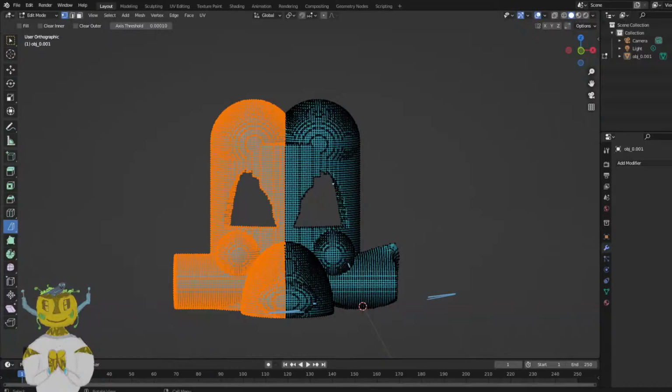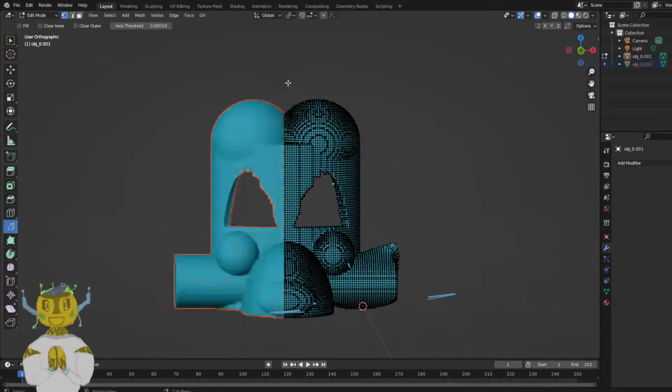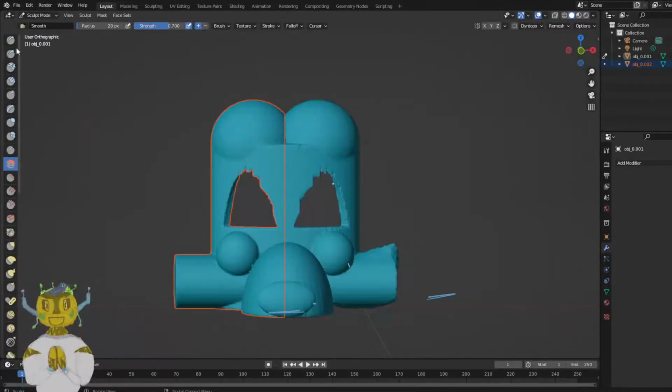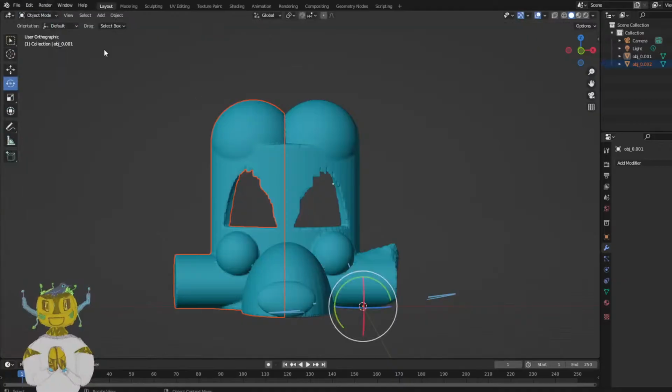Right, this one. Okay, so then go into Select, Selection. The new pieces will be open. Select one of the objects. Now you have two separate objects. And then, right, we need to press P for the separate menu. P, Selection. Yeah, separate by selection. So now we've got two parts we can work with.